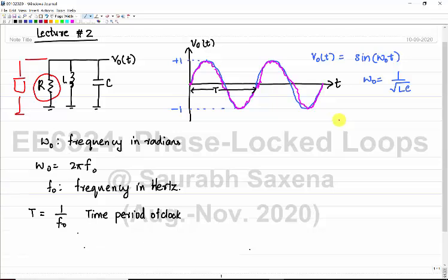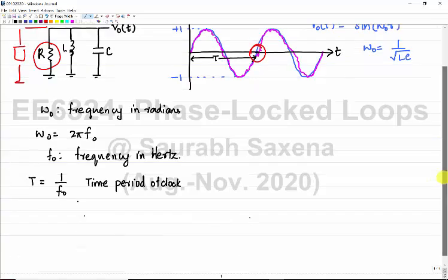But when you are going to do that, you will have variation in the output clock waveform, and that variation is going to change not only the amplitude maybe, but also the zero crossing of the clock. And if you remember, we were looking at zero crossings of the clock when we were trying to send data at a fixed rate, like fixed megabits or gigabits per second.